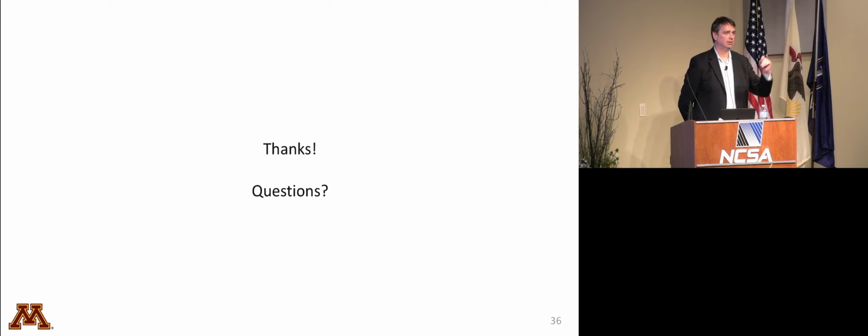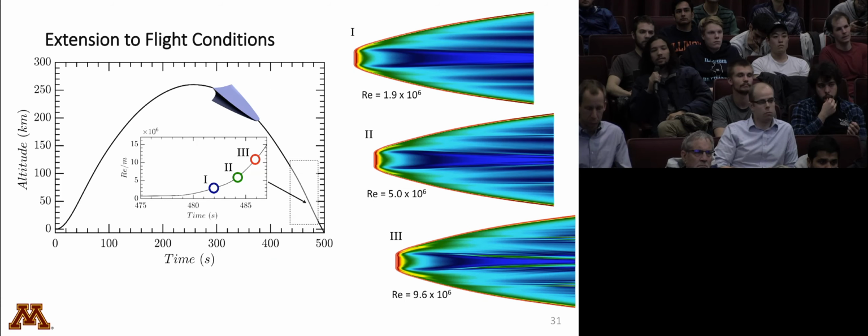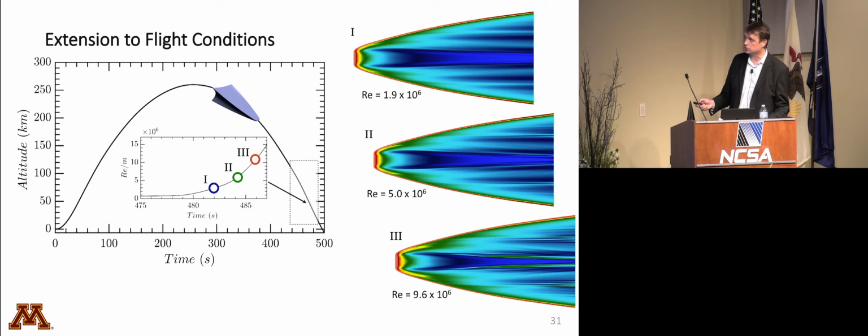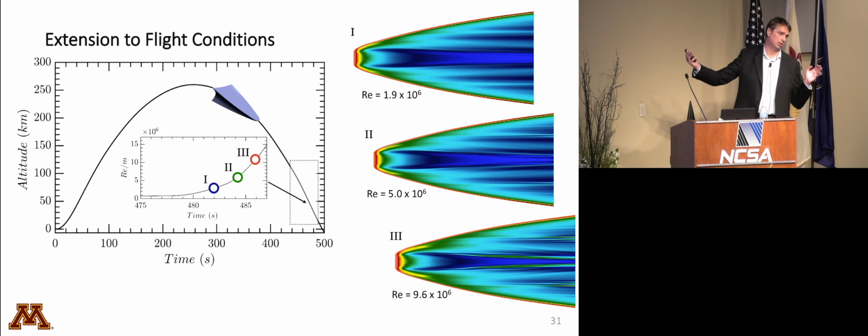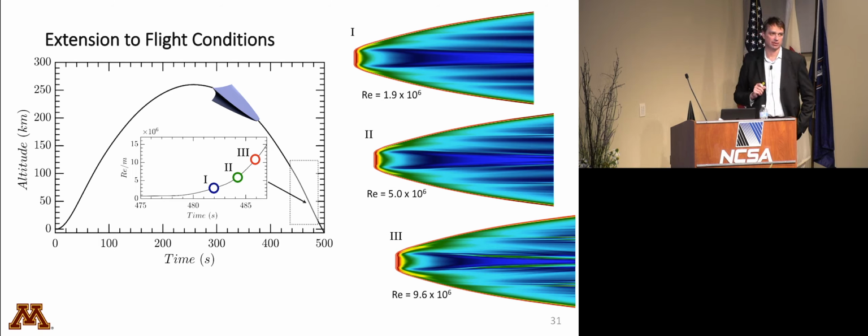Is the nose cone just falling when you're taking measurements, or does it have something behind it to guide it? Yeah, okay, I didn't say that explicitly. So during this trajectory, what's shown here is just the nose, but it actually is a captive carry, so it's dragging with it the second stage of the booster, which has these big fins on it. And so that is really what keeps it pointed down. You're right, any aerodynamicist would say, good luck with that if you're going to try to fly that without some kind of stabilization. So yeah, it's going to carry the second stage.